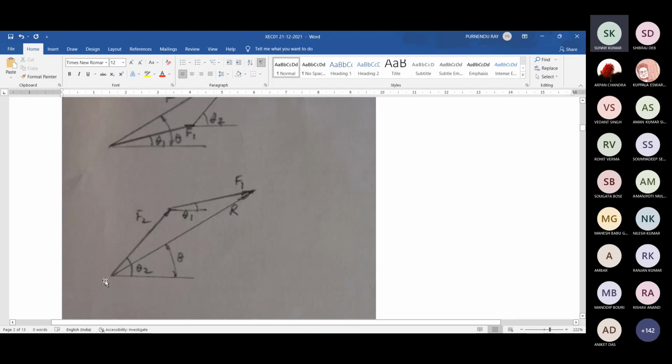Then at this end, draw a line passing through this point. Extend it. We do not know where it will terminate. From this point, draw another line with that given direction, and we draw this extended line. Get this point of intersection. This will be the vertex of that triangle opposite to this side base. So either two sides, one angle, or one side, two angles, or three sides in length. But all three angles will give you infinite solution.